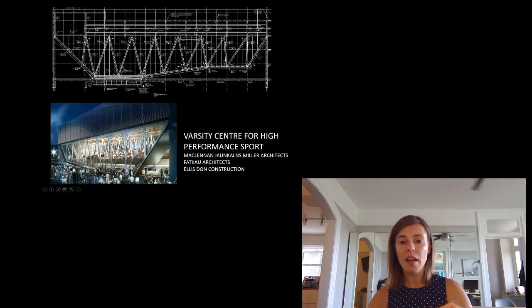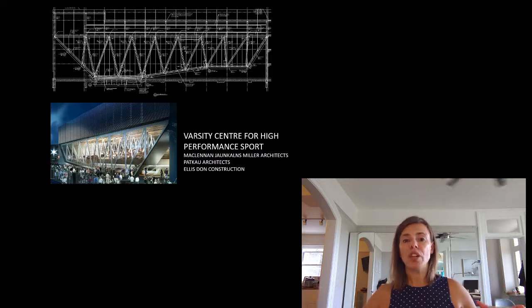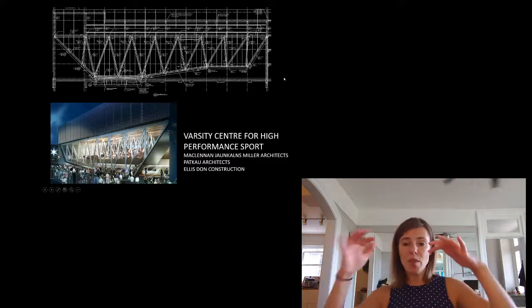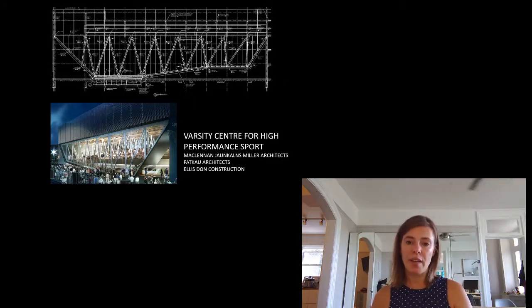There's nothing underneath it. Underneath it is a field house, or basketball and volleyball court, for those that don't know what a field house is, which is larger than this footprint right here. So we couldn't actually touch down the steel trusses right there. This is just one of the trusses. The interior trusses are only one story deep, so from here to here. And the rest of the building is hung from the underside of those trusses. So we have basically a very long bridge acting as a building, supporting floors below. A really unique structure in so many ways.